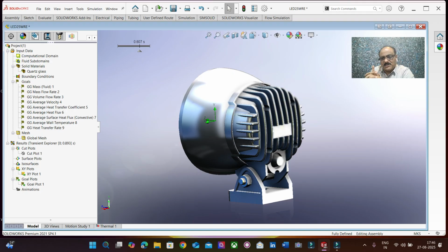So in between the nodes, let us say a tetrahedron has 4 nodes, and on each surface, the centroid of the surface, we are going to identify the value, the physical value, whether it's a strain or stress or temperature. It's like the Gaussian integration.